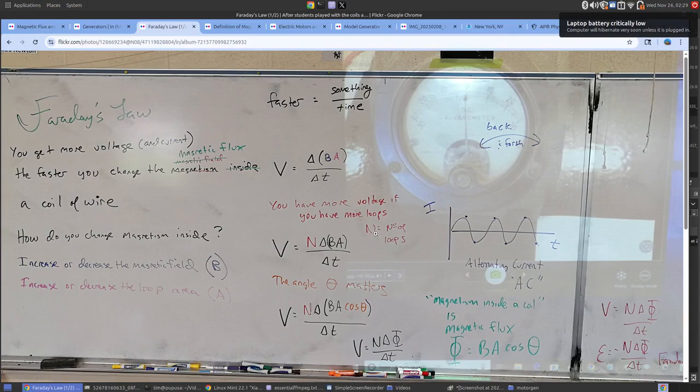Just a quick summary of the key points. When you create an electrical current by rotating a coil of wire, you create an alternating electrical current. And that's the native current that generators make. We can get direct current generators by introducing the idea of commutators and brushes to switch the direction of current for us as we rotate. And we should also understand that motors and generators have symmetry to them. If you put in the work and it makes electricity, it's a generator. If you put in the electricity to get work out of it, it's a motor.